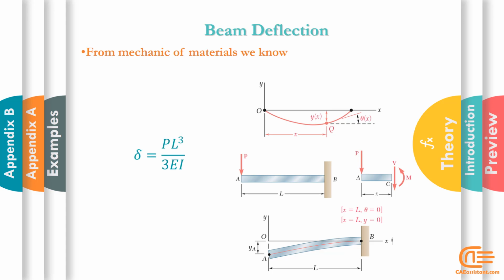Now, if the cross-section, load, boundary condition, or any other parameter changes, then we have to calculate the integrations again. You see how much calculation is needed to calculate a simple deflection of a beam. Notice that beams should be supported in such a way that the reactions at the supports can be obtained by the methods of statics. Otherwise, the problem will become more complicated.